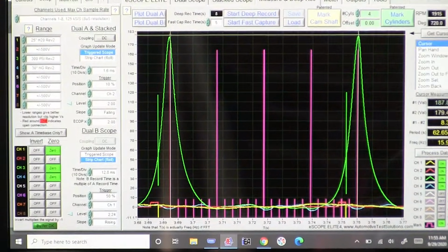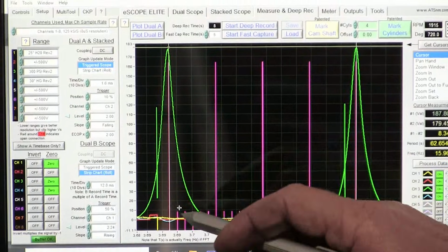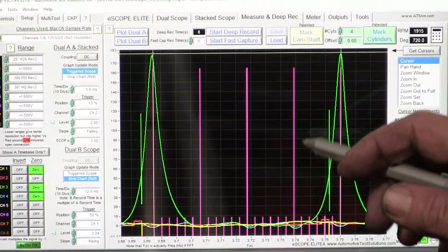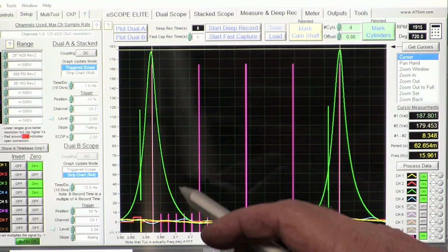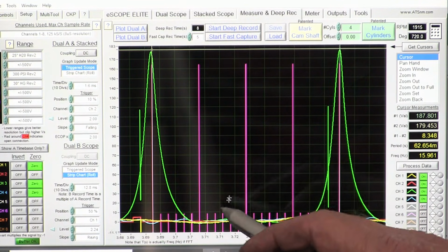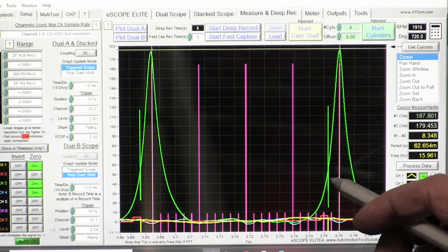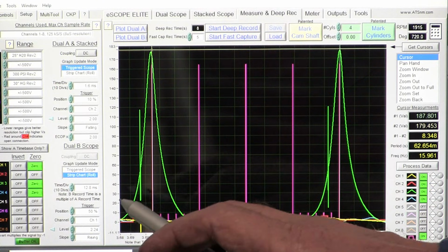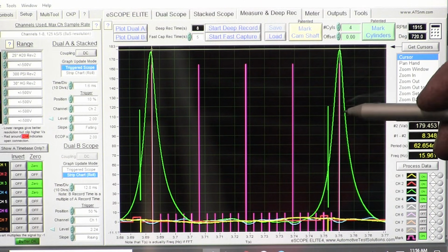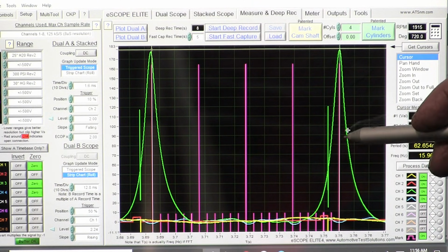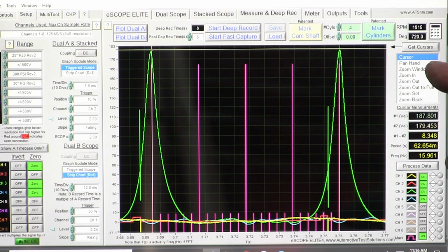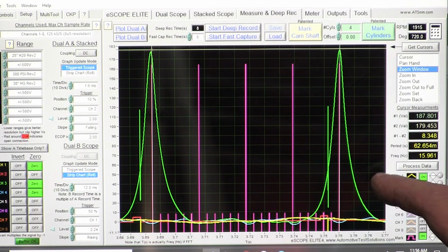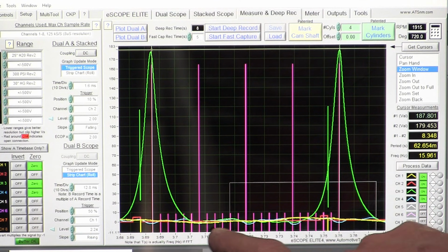And then we want to mark them. Now we have this as top dead center, bottom dead center, top dead center, bottom dead center, top dead center. This is the power stroke, the exhaust stroke, the induction stroke, and the compression stroke. So now that we have these, I can look and I can see the towers aren't leaning, they're pretty even, so that's a good thing. If they're leaning, it tells me I have a mechanical problem. At this point, they're not really leaning.